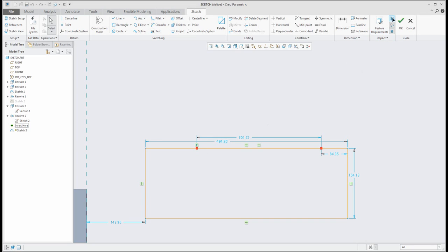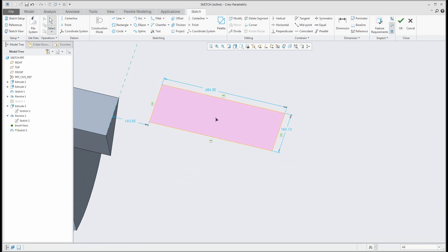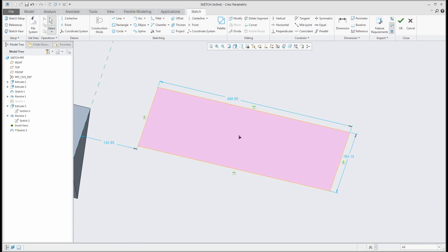And the last thing here is the overlapping geometry. If you select this icon, the system will show you directly in the sketch the overlapping geometry, and you can select delete unwanted edges or lines, and then the system will show you the correct closed loop. Yeah, you can see if I switch off, it's not possible to see the closed loop. If I switch on, it's the default, it always shows. The system will always show me this information so I can check it.